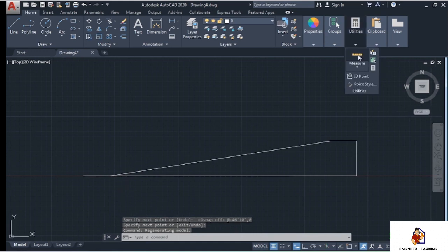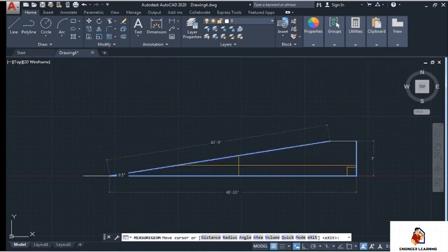Here we have formed a ramp which goes down in the basement parking of a multi-storey building. The max slope that we provide is 1:6. That means it roughly falls down 1 feet after every 6 feet. In degree, it turns out to be 9.5 degree slope.